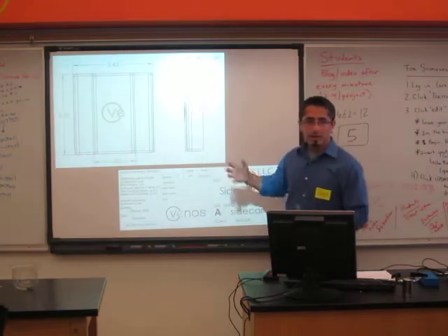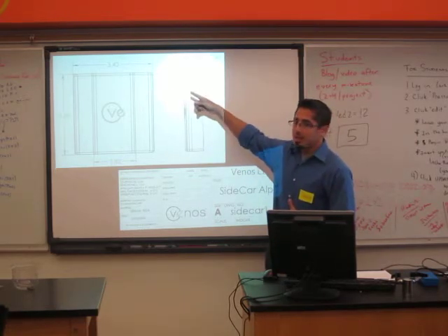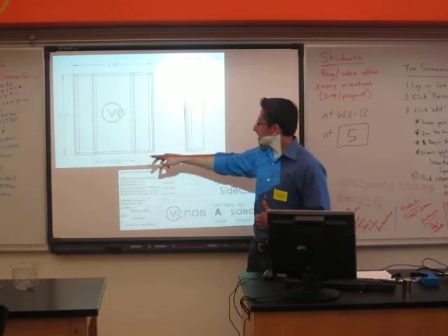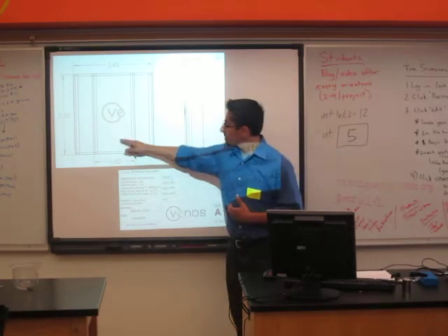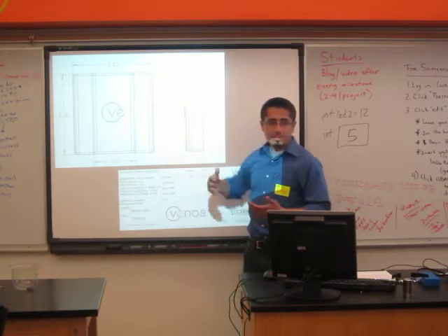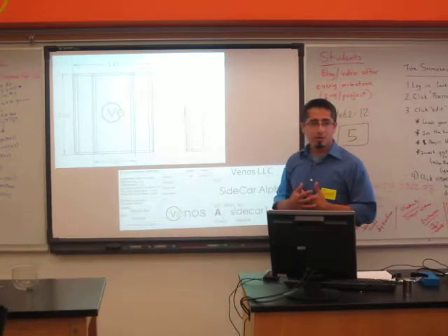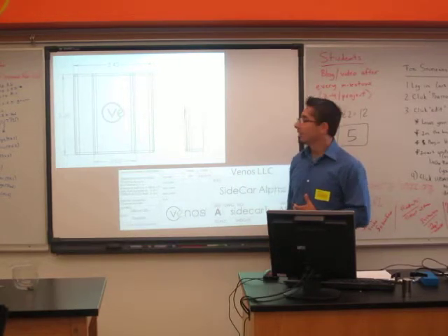If you have your shape and you need to cut a block or a rectangle, you want to get your basic dimensions. I need to know how wide it is, how long it is, how tall it is, and how deep it is, right? These are basic dimensions. I'm going to put a hole, like right here. I need to know what the diameter of that hole is. Does it go all the way through? Simple stuff, but if you ask me to go cut it for you, I need to know those. Otherwise, I'm going to return you a part with only what I see.